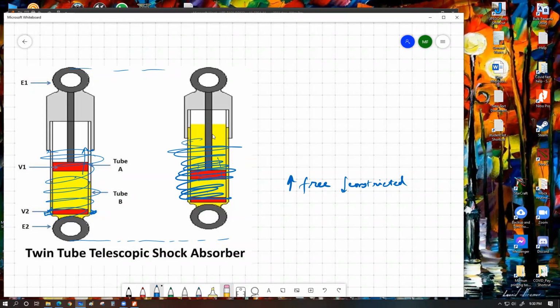Explain this again. Okay, whenever this shock absorber experiences a force in the upward direction, which is happening in this case, this piston is coming down because actually the lower structure is going upward. So this oil would undergo some amount of compression because this is pushed up. That will allow free movement of oil from this chamber into the upper chamber above the piston, in which process the spring will become compressed. The spring will practically resist that compression, and once the spring is compressed enough because of the upward push, when those two forces become equal, then naturally what should happen?